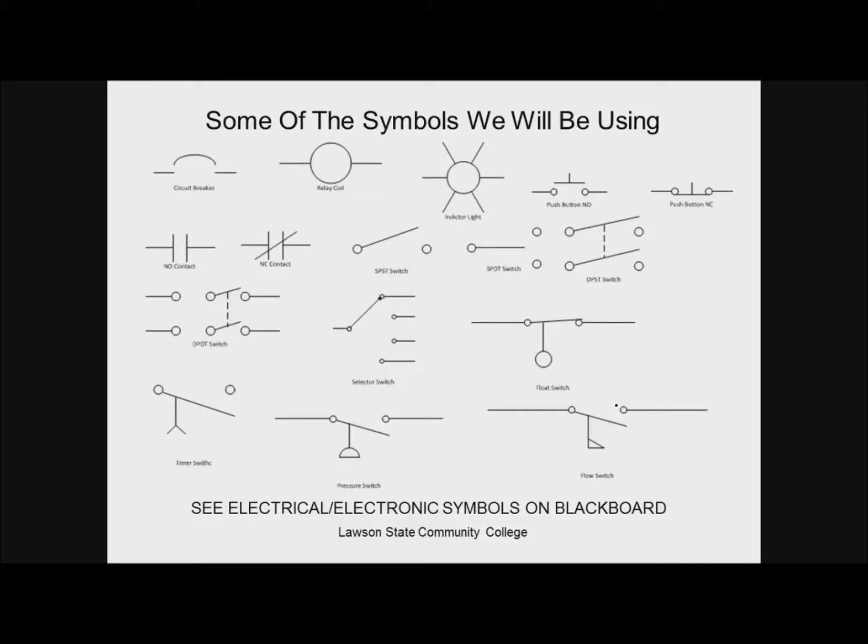Now, when we get into relay contacts, these are the contacts that are being controlled by that coil. We have two types of relay contacts. We have normally open contacts, and we have normally closed contacts. Y'all see the difference in the symbols. Okay. So a normally open contact does not have the bar through it, or the line through it. The normally closed contact does. So what does that mean? Well, that means on this first one, if I don't have voltage across that coil, and this is in series with my light, so let's look how we would do this.